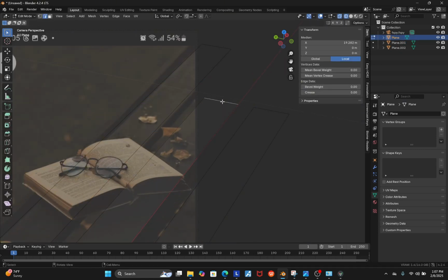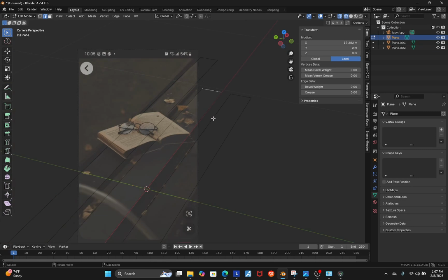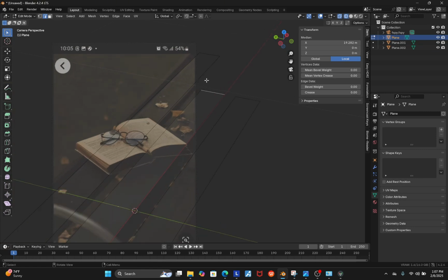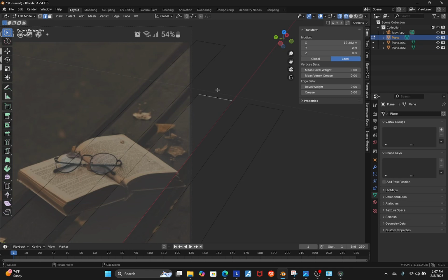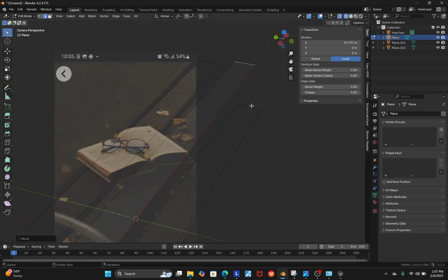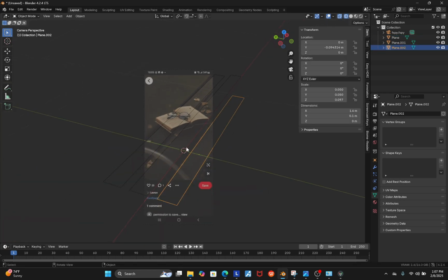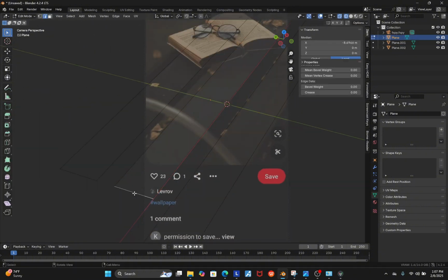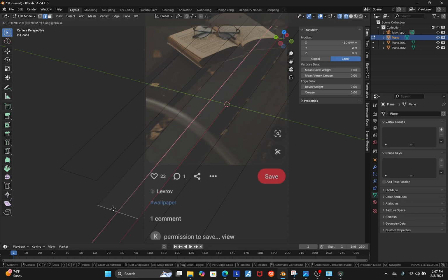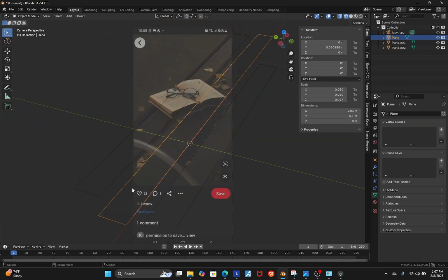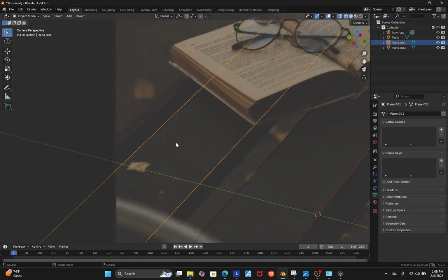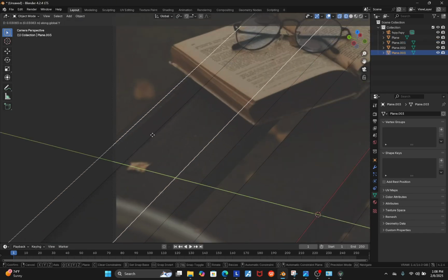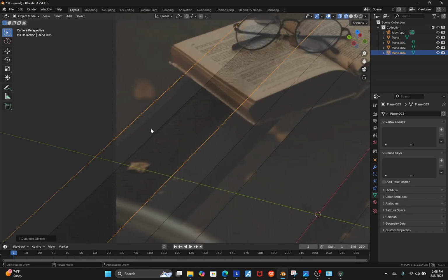You can use Alt 3, but I want the three of them to have different object properties for the things that we're going to do later. So just press GX, and then also select this one, press GX. Just do everything that's going to be visible inside of the camera view. And also I can press Shift D and then Y again and place it something like this.